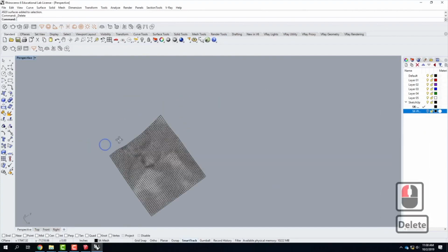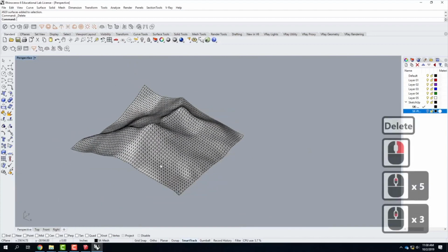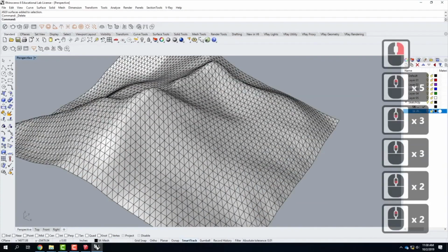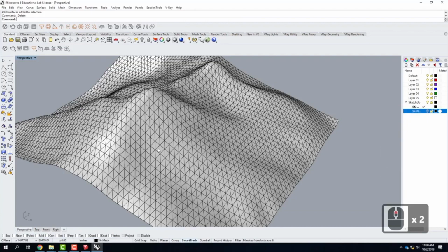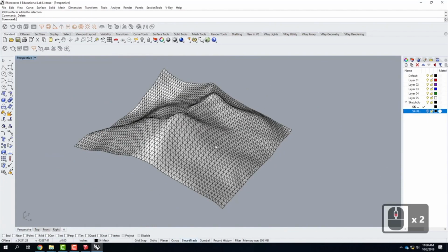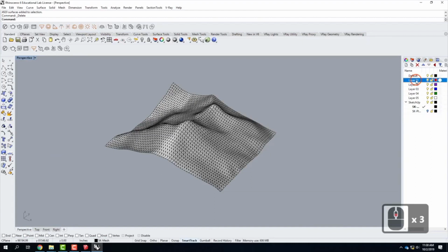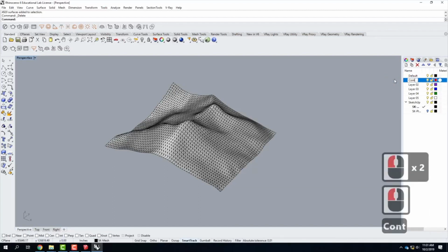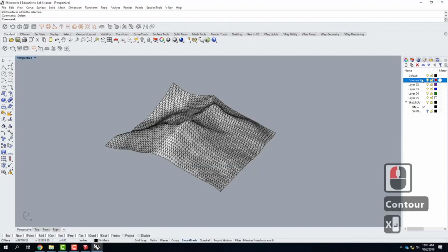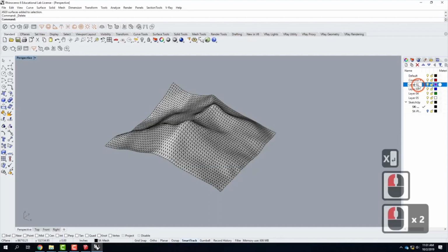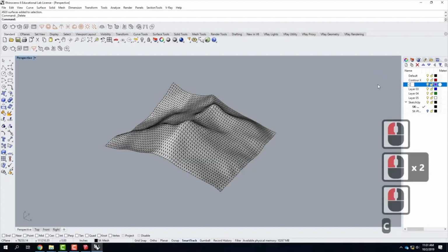So instead of doing it that way, we're actually going to use a command called contour to give ourselves some lines. And this should start to look a little familiar to how we created the cushions later on. So I'll show you. So let me work with my layers. The more organized you are here, the easier this is going to be. I'm going to take layer 1, I'll double click on it, and I'll rename that to be contour X. You could call it contour 1. And I'll take layer 2 here, and I'll rename it to be contour Y.